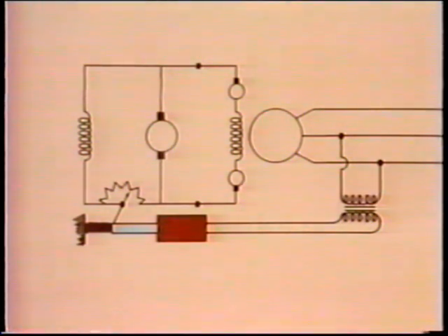Our system will work the other way, too. If the AC generator's output voltage increases, the system will act to decrease the excitation going to the AC generator's field. We now have an example of a system for automatic AC generator voltage control. We've seen that the control system will act to either raise or lower exciter output voltage to maintain a constant